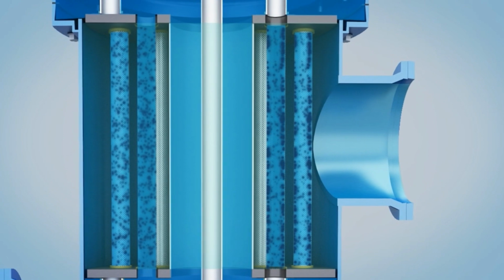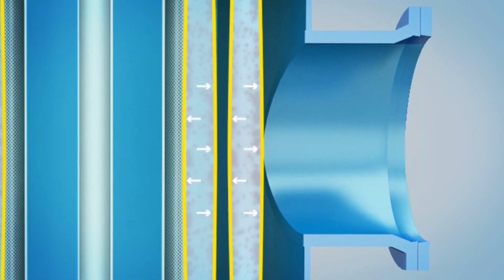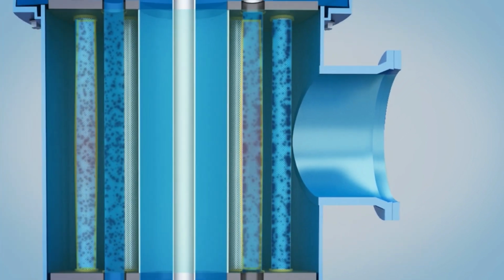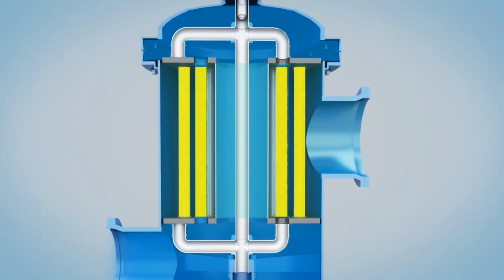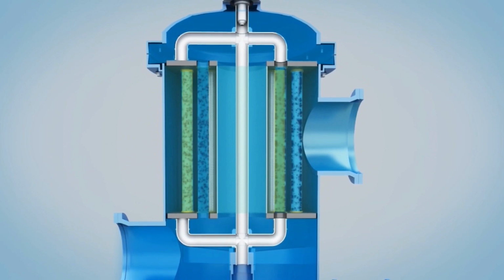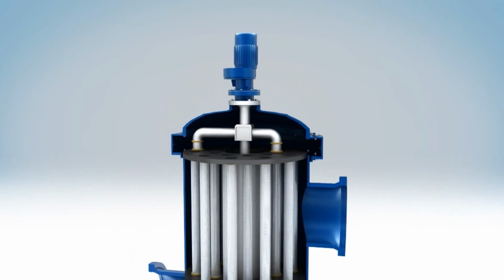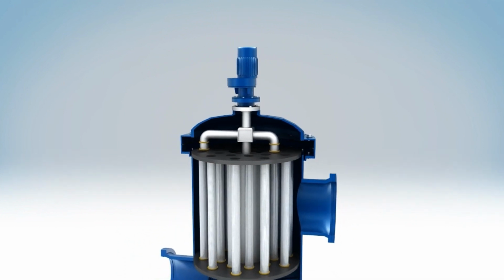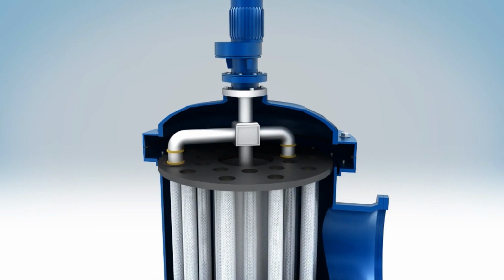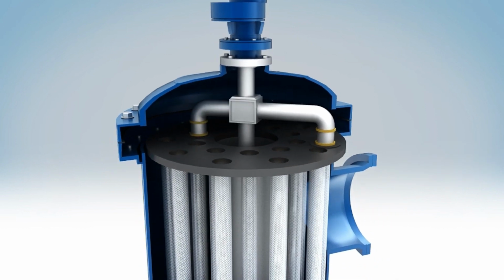When the pressure drop between the inside and outside of the filter mesh rises to a set value, the filter will operate the back flushing process automatically. The filter meshes, which are open at both ends, will be alternately flushed in sequence from above and below. This action doesn't interrupt the normal operation. The flushing arm on the top of the filter rotates by gear motor and covers the upper opening of the filter mesh.